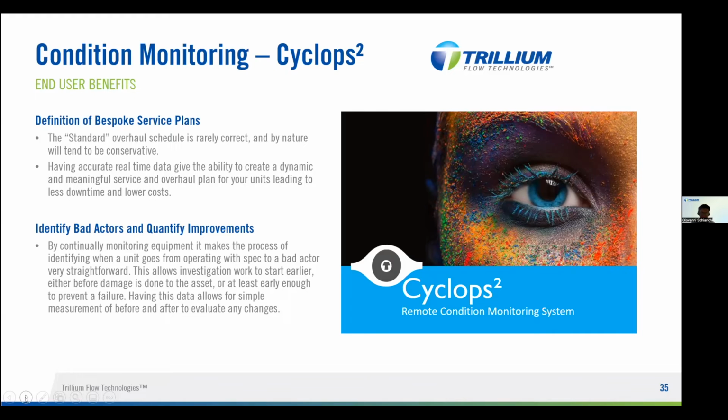That is, meaning if the pump is operating far from a best efficiency point, if the pump is operating out of the curve or not in the preferred range of operation, and also how the pump is maintained. That is, if we can identify bad factors in terms of poor or wrong maintenance.